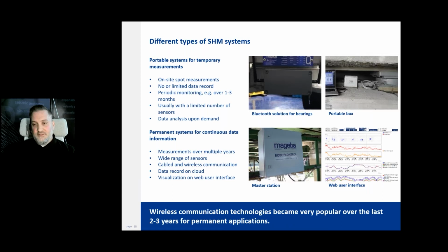And so, as I mentioned just a couple slides ago, there are 2 general categories of structural health monitoring systems. That's the short-term temporary portable type and the long-term permanent automated type. Starting at the top here, we have the short-term system, typically to get a specific set of data about a particular thing. Andrea will actually show you a really great example of where this was extremely useful. And something like an intervention work would be a great example of use for the short-term systems. And then, of course, typically a smaller quantity of sensors, but the same sensors nonetheless, typically just fewer of them.